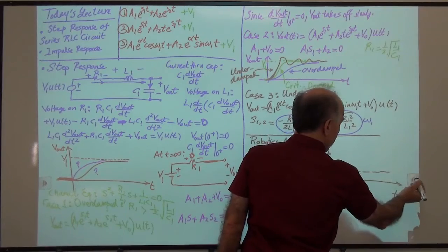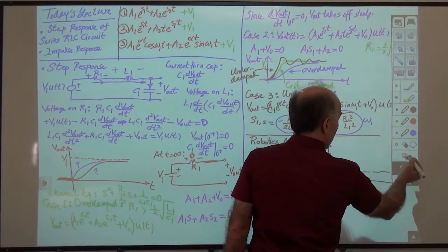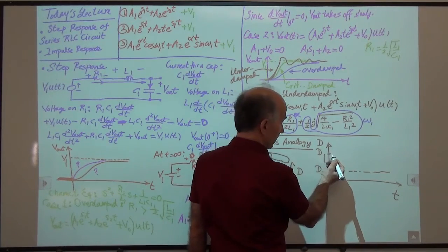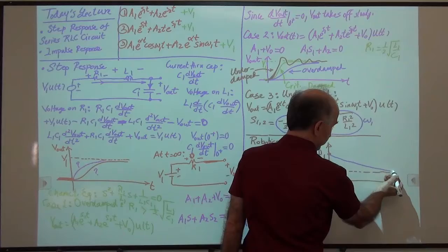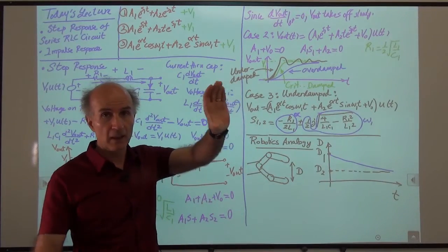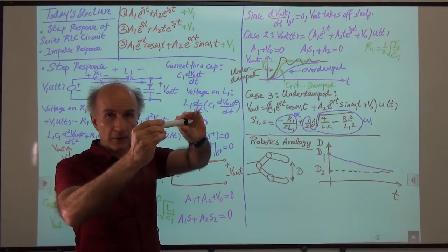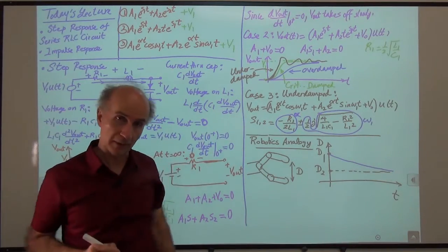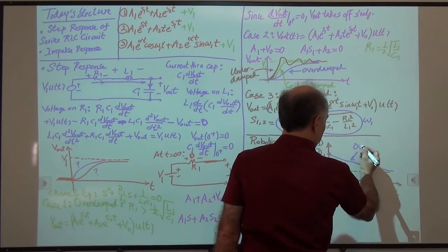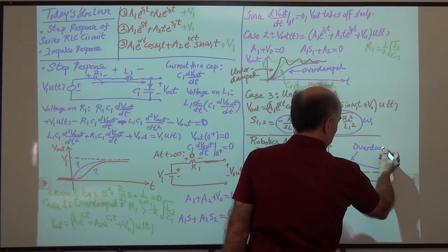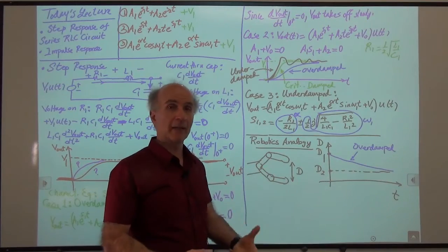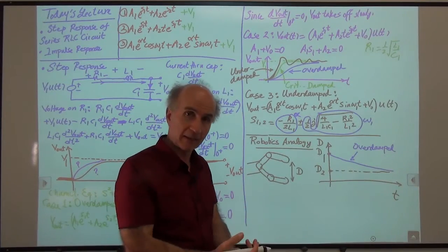It could be that the response is overdamped. So it goes from D1 to D2 very slowly, goes like this. That's a conservative solution, meaning that we want to make sure that it comes down slowly and it touches the egg and then grabs the egg and puts it over here. So that would be an overdamped response. What's the disadvantage? Well, it takes too long, so we can't process that many eggs per day.